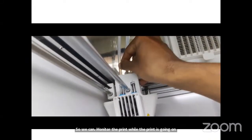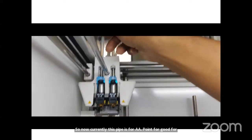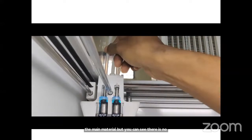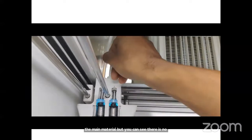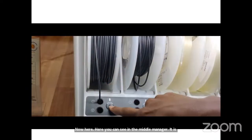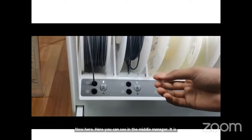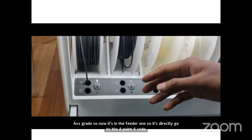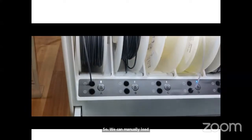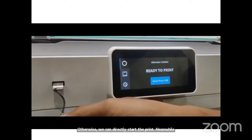So now currently this pipe is for AA 0.4 core for the main material, but you can see there is no material inside this flow line. So we have to give the material, we have to assign the material. Here you can see in the material manager, it is ABS gray. So now it's in the feeder 1. So it directly goes to the AA 0.4 core. So we can manually load the filament. Otherwise we can directly start the print. Meanwhile it will take the filament inside.